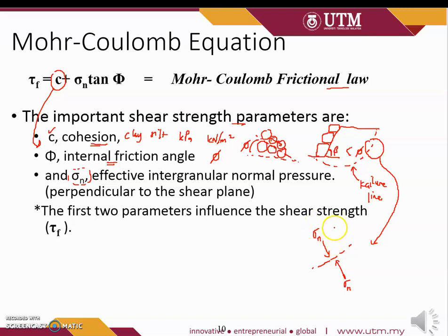As long as we know the gamma, what type of soil it is, is it dry soil, so gamma dry, moist soil, so gamma bulk, or it has water in it, so we need to calculate pore water pressure, then we can calculate the normal stress. The normal stress can be either in the total condition, total stress, or in the effective condition. I hope you still remember, effective stress is normal stress minus the pore water pressure. Similarly, at the failure lines, we can have a tau that resists and a tau that mobilizes the failure, tau F.